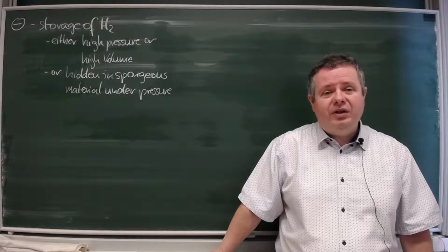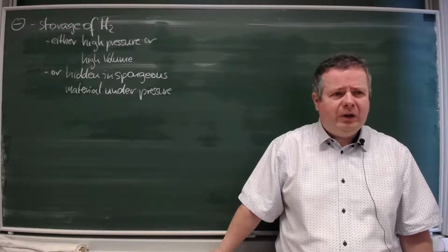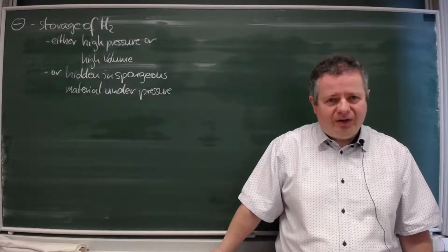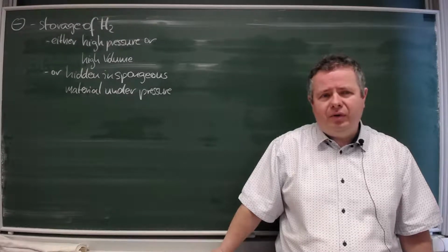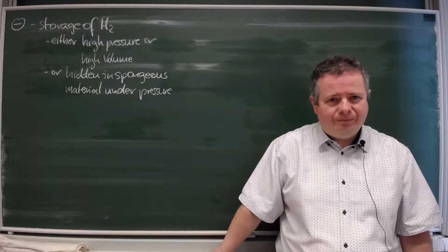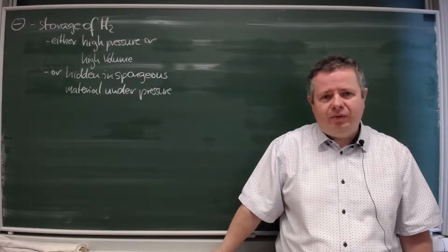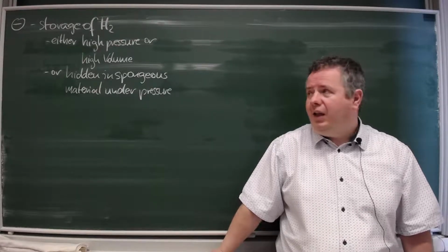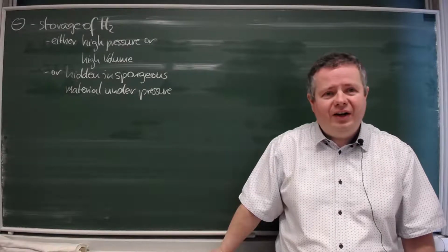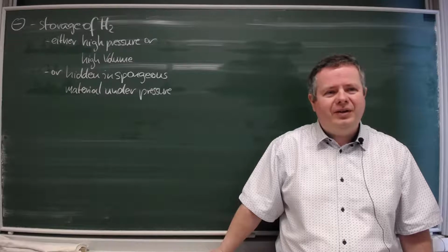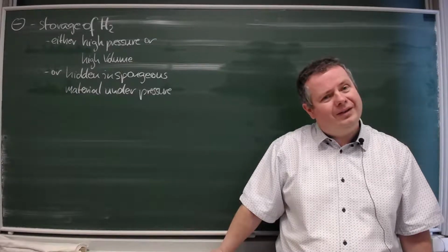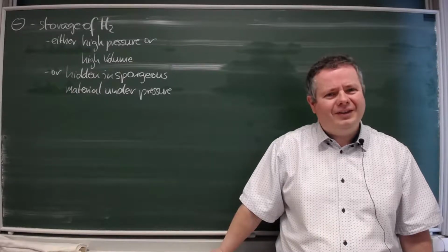You get braking circuits in the hydraulics, you get 100 to 150 bars. In airplanes, you get circuits up to 400 bars. But it requires specific materials and quite careful handling. And then you get your fuel cell car, inside which you get the hydrogen at 700 bars. 700.